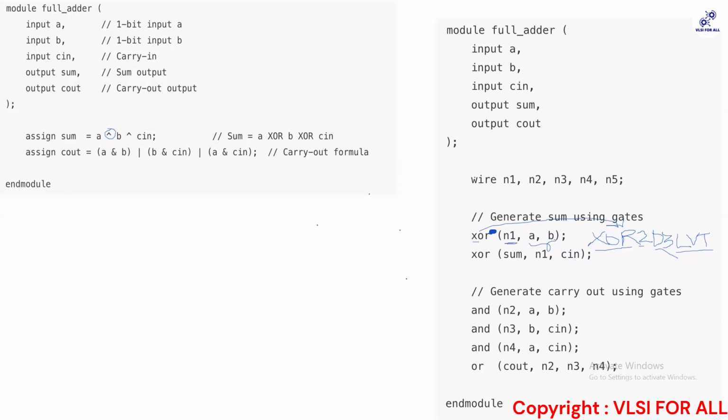There is not a much big difference, right? Specifically, for example, let's say in your library you have something, and let me say it is 3x3, the naming convention by the companies, 3x1 drive strength 5, and let me say it is HVT.